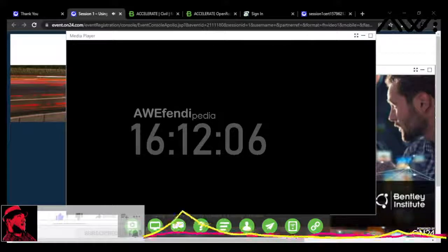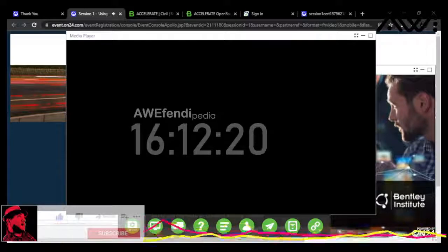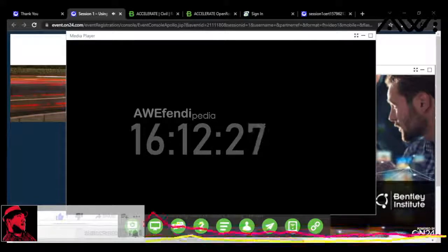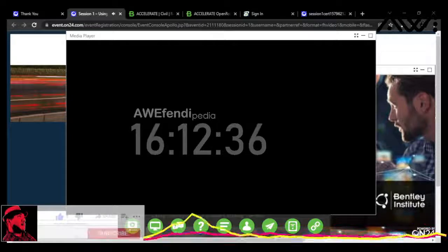So let's go ahead now and start doing some edits. First thing I'm going to do is turn back off the background streaming. And there, we're just back to our graphics now. Typically in a workflow now, you're going to clean up just errors that were in the collection. Let's zoom in a little bit here to the left side of our survey, and I'm going to go down to the bottom about where this median cut is. It looks like there's a couple of driveways down here, and I can see I kind of have a bust here that I want to fix.